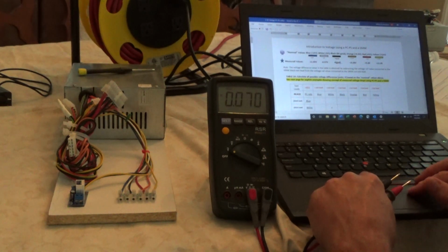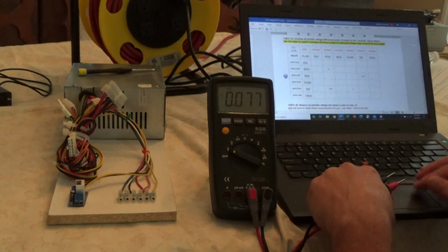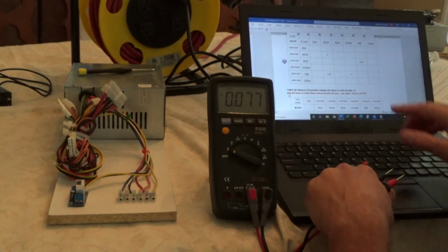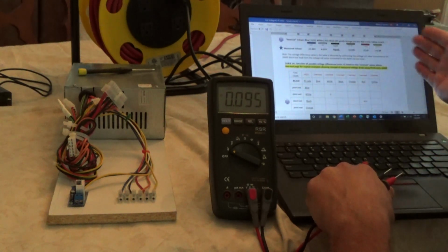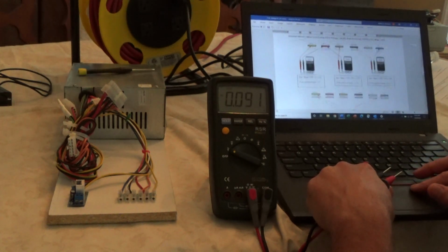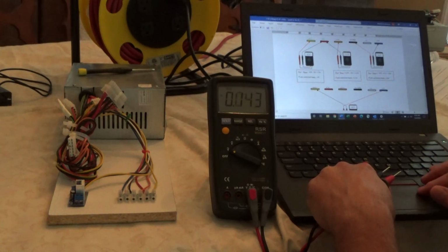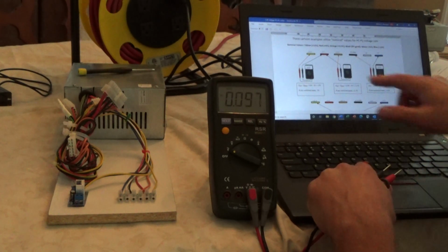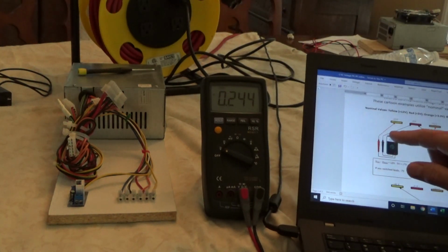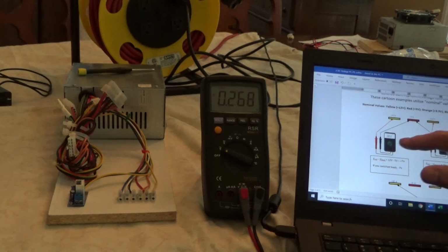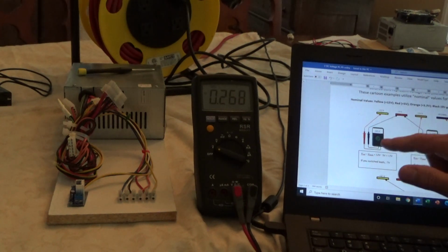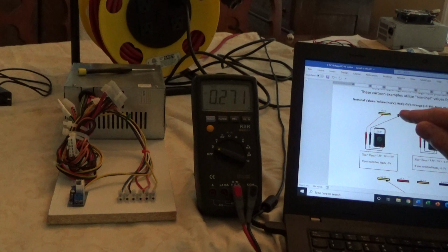So what you need to do is take those nominal values and fill in this chart. See, I've got a little sign here, nominal values, and you fill in this chart based on what the potential difference would be if you measured it with a multimeter based on those values. And on the second page are some examples of what you would see. So basically, for example, this first one right here, if you put the red probe on the plus 12 volt rail and the black probe on the plus 5 volt rail, you would get, what you do is you take the red probe and subtract off the black probe.